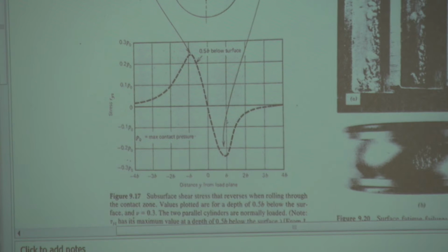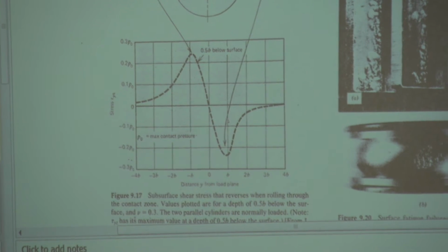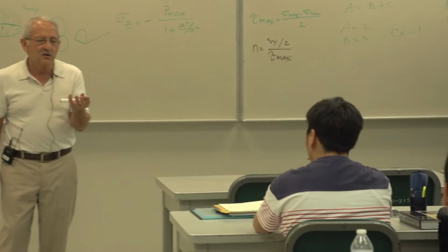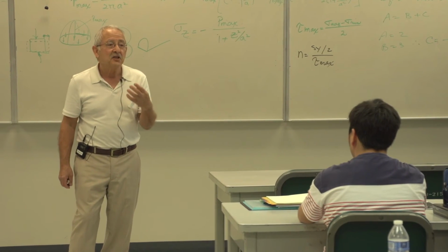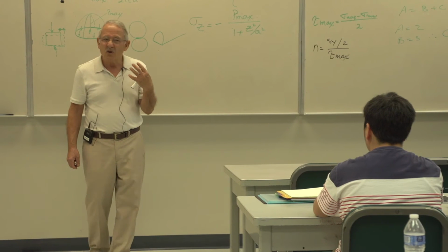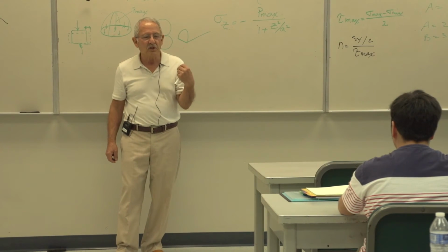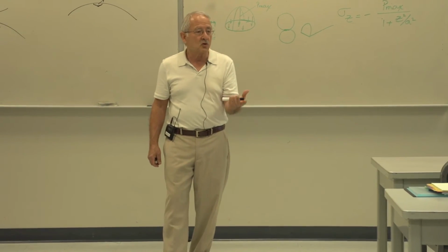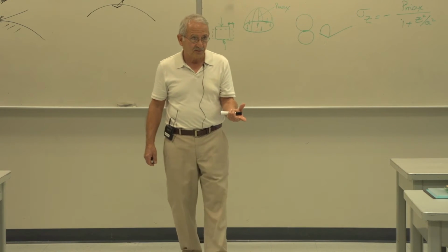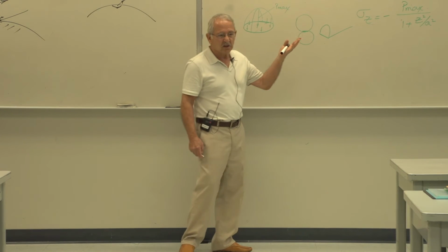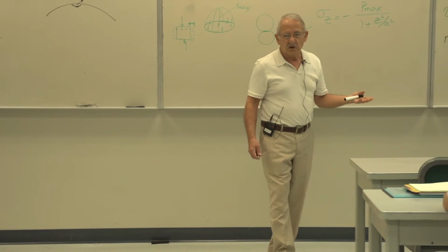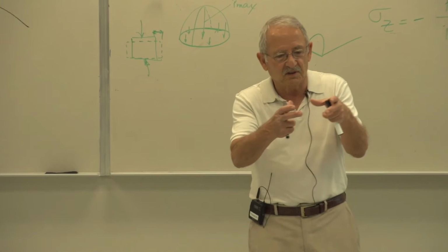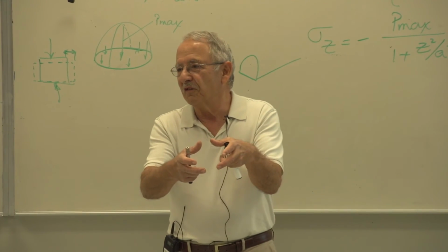Is it similar to like holes in the roads? Insofar as the holes in the roads coming from cracks in concrete, yes. But no, the road is really not like that. There are two reasons for that. One is that the road is, of course, concrete, right? It's a brittle material. And although you do have these stresses, they're not substantial. You got a 5,000-pound car, for example, and 4 wheels. It's only 1,000 pounds per wheel divided by 4 inches squared. That's 250 psi. That's nothing.